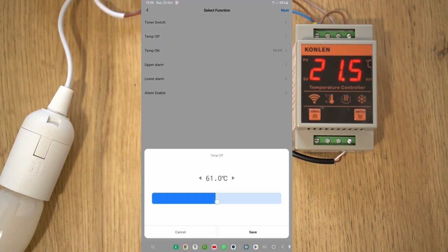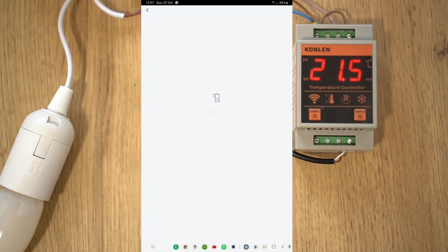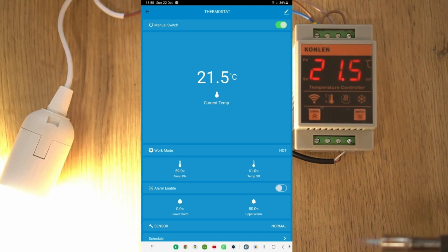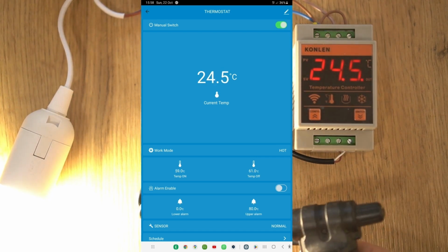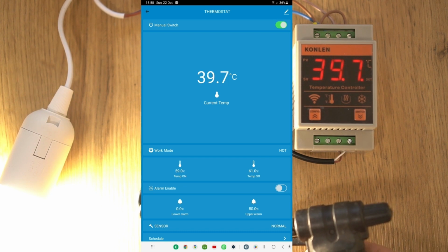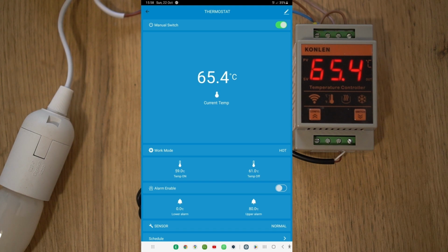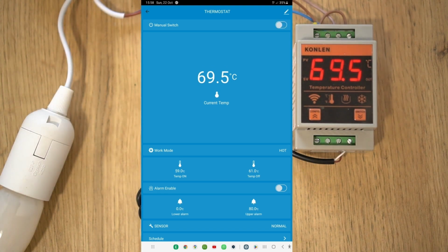This is thermal inertia. Continue adding as many time points as required to our daily scene, changing the parameters to suit your needs. This process allows you to create an infinite number of points to control the boiler each day. I don't know if there is a limit to the number of time points per scene, but you can easily add 10. In each time point, you can set your own temperature parameters for switching the boiler on and off.